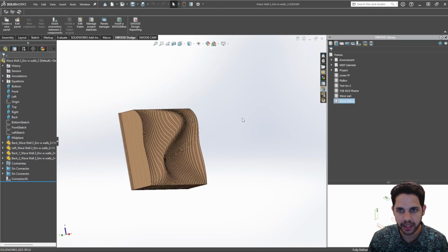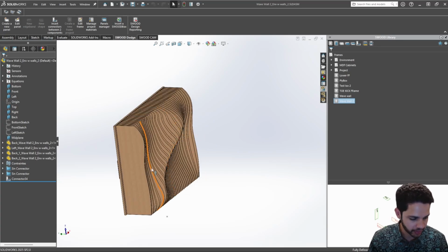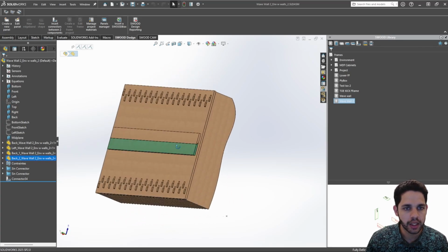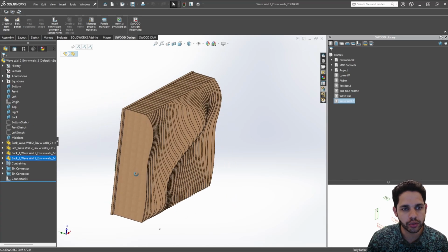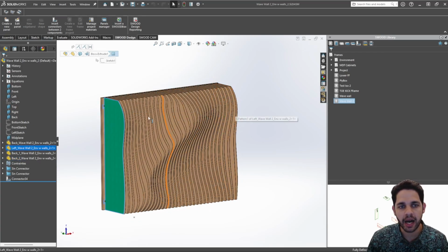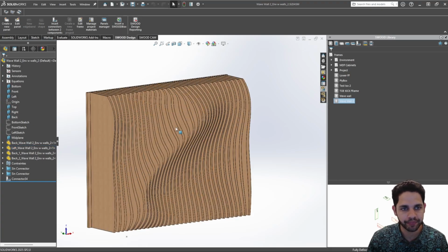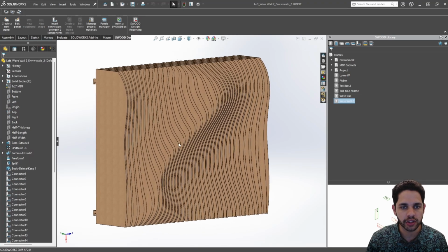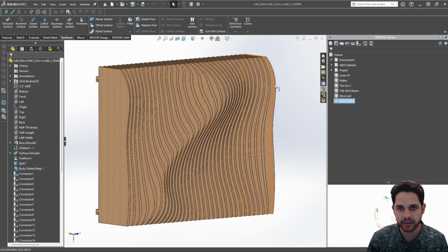So this is a copy, again, not the original frame. What we'll do is start off with a save bodies operation. I'll open the part in position. It'll make each one of these its own part, but it's referencing this original part file.